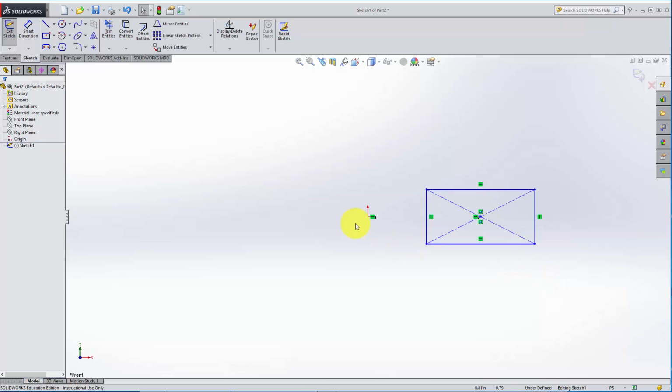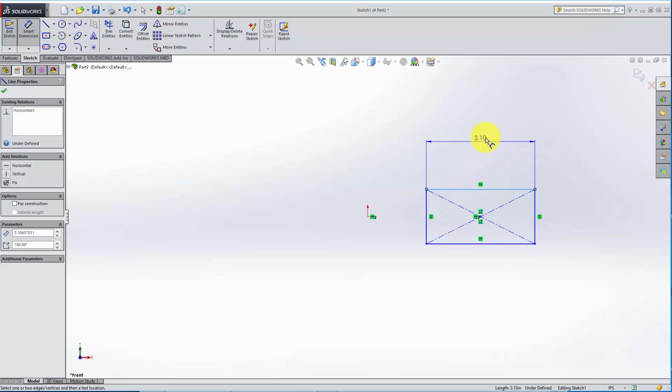And same thing with the dimensions tool. I can go to smart dimensions, but it's faster if I hold the right click down and move my mouse a little bit. There are several different tools. There are 4 of them, and the top one is the dimension tool. So I'll just slide up until I select that dimension tool. I can click the top line.